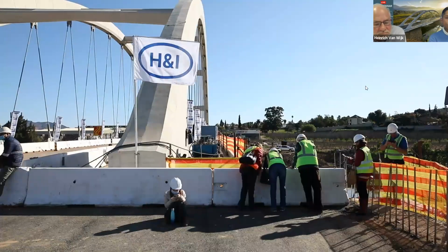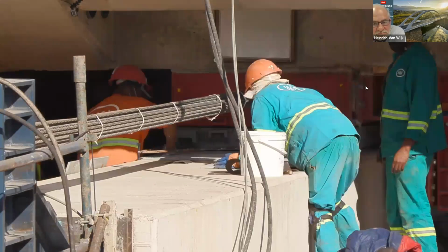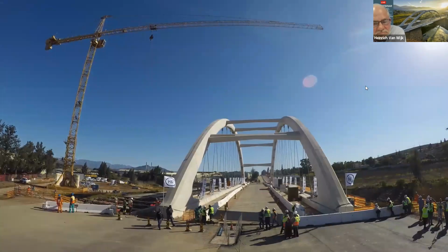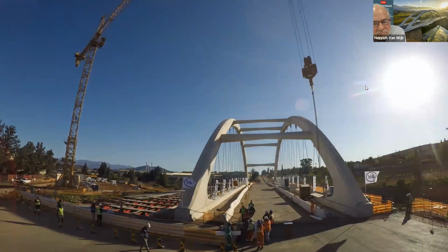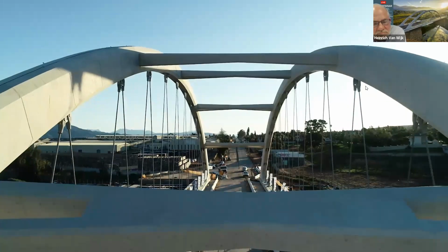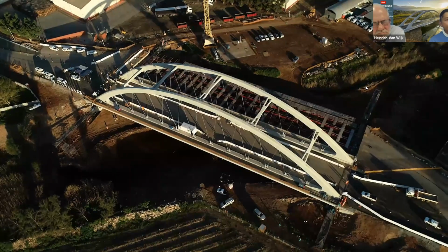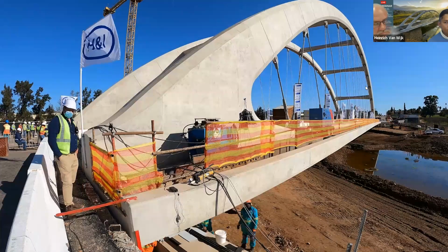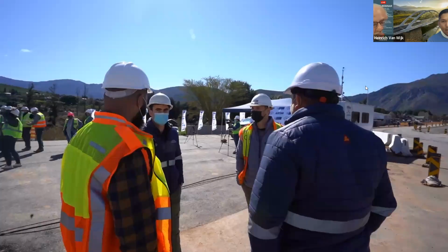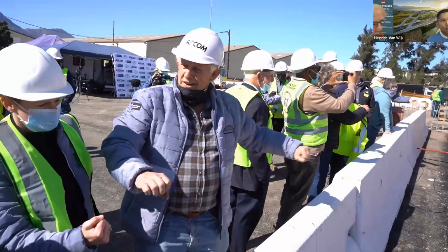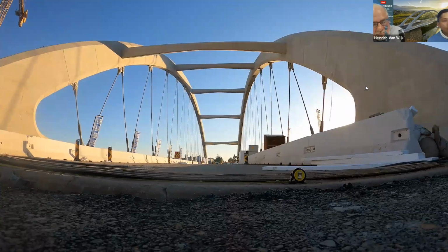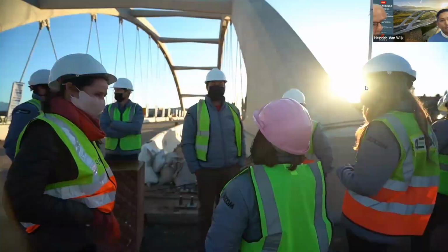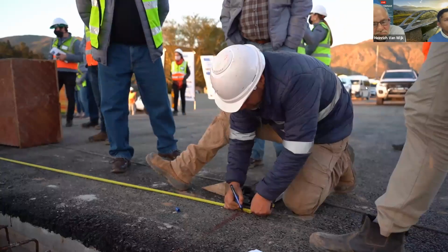I think we're referring here to the hanger strands. A big part of the measurements that you take on site is structural deformation and elongation of cables, and I think our computer models were quite accurate with calculating the deformation of the arch. Of course, it's not as accurate, which means that our cable elongations were relatively accurate, but they wouldn't be as accurate as the elongation comparison for a pre-stressing system.